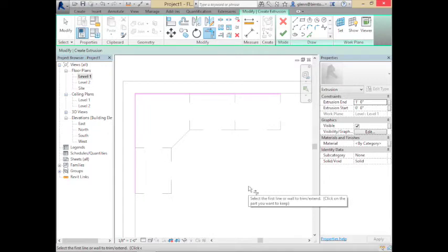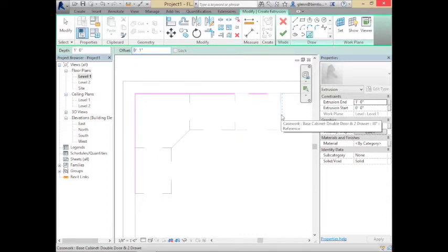Then on the front, this is where we'll use the offset, because what I want to do is typically countertops, they hang over a little bit. They have that little bit of difference, so I want a relationship. I want it to line up with the edge, but I also want to give it that 1-inch overhang. So I'll choose the pick tool again, but I'll put an offset in here. Something like 0.1 or however many inches I want that to overhang. And then when I hover over the line, you see it has that little green dashed line to the right of the edge of the cabinet. That's where it will place this. If I complete, I'll offset to the edge here.